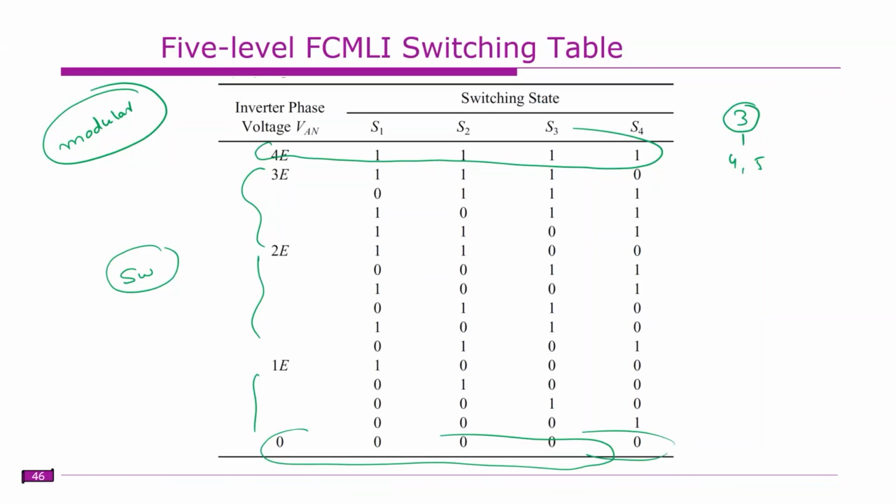For example, in the case of the cascade H bridge, suppose you identified that 3 H bridges are enough for the initial time being. In future, if you forecast that the power requirement is high, you can add 1 or 2 H bridges per phase. This is known as scalability. This scalability is possible only when the structure is modular.